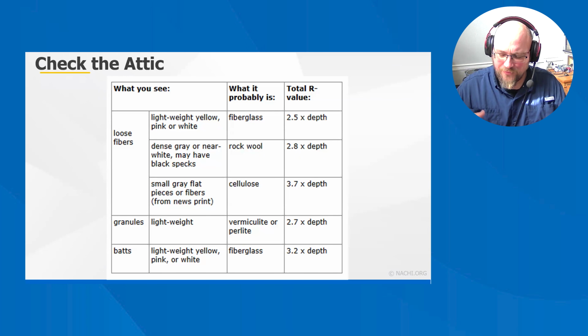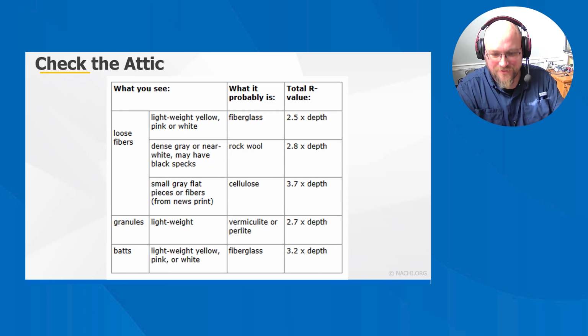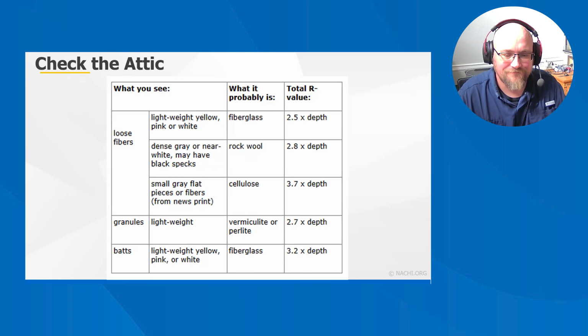And so you feel like even if you did have a little path going through the attic, you might still, what do you call that? The crown of your foot? Is that what that's called? Crown of your foot. You step on the middle of that joist, but your toe and your heel still go down on both sides of that joist, and you could potentially step on something, a can light or whatever, and push that down into the ceiling. So just make sure you're safe, follow your SOP, and don't put yourself or the home in any danger.